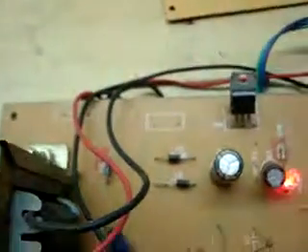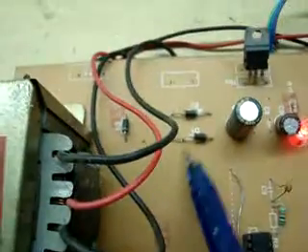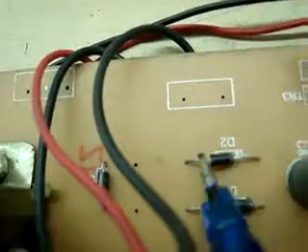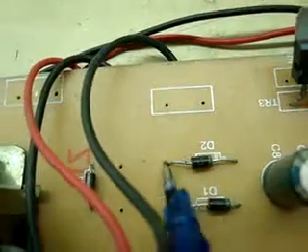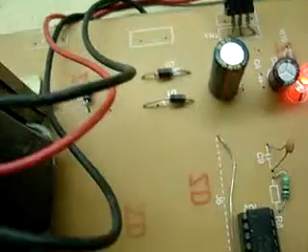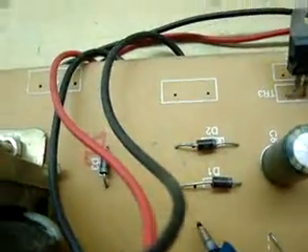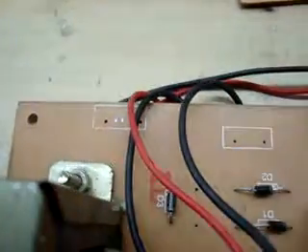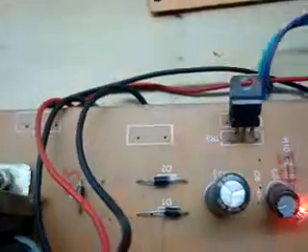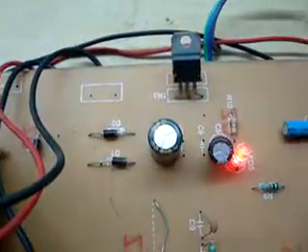To convert it into DC, we use a rectifier circuit, a full wave rectifier. These are diodes. The silver side is your negative and the other side is your positive, and these 2 sides are common and given to the positive of the capacitor, and side by side with a voltage regulator 7805.